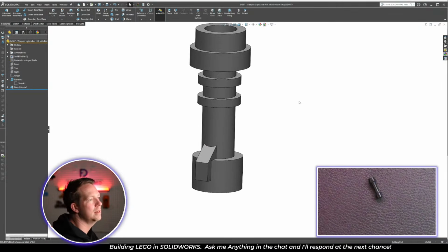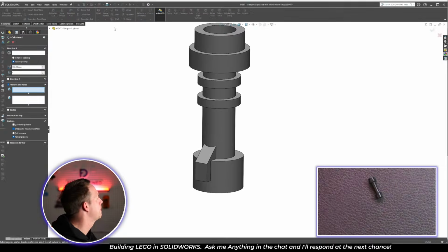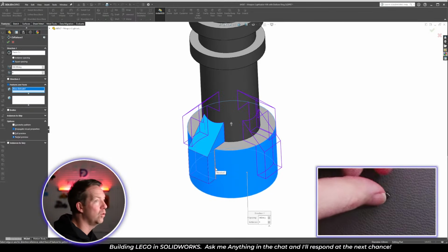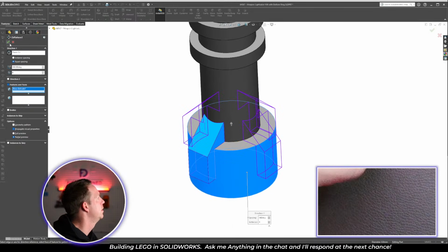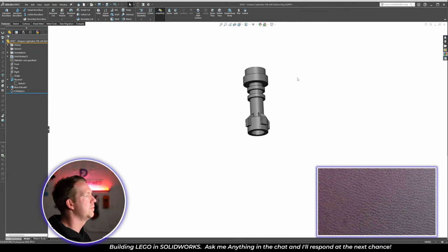And then I'm going to put that in a circular pattern feature. Under linear pattern, press circular pattern. We need something to revolve around the pattern. We can just use this round at the bottom. And then for feature, we can just click on the feature in the viewport. We get the preview. There are only 4 of these being rotated around. Press OK. And there you have it.